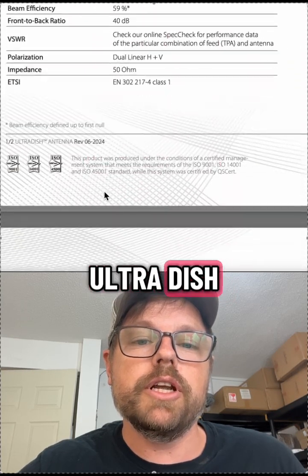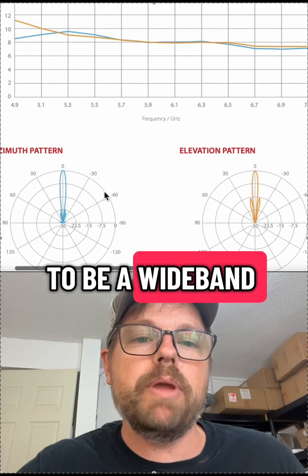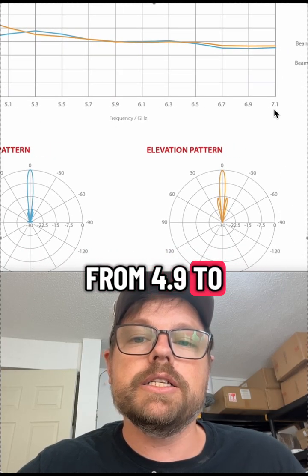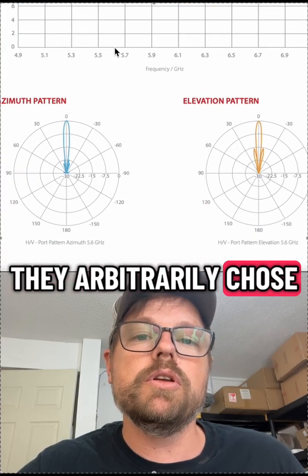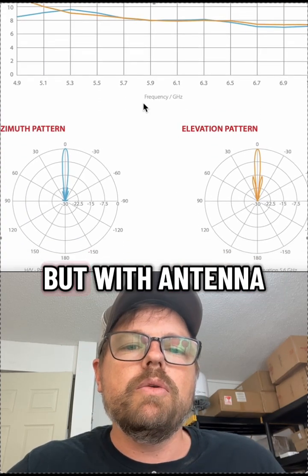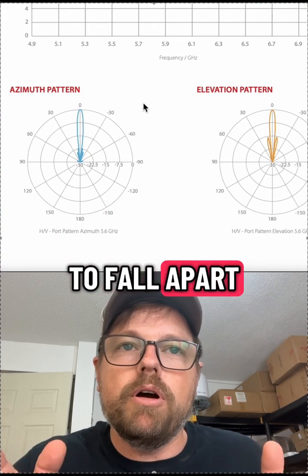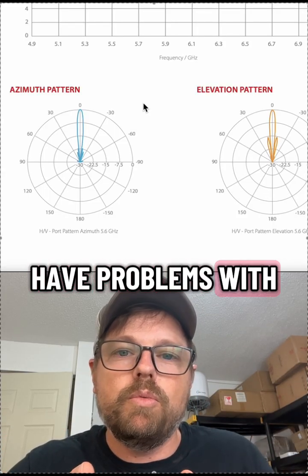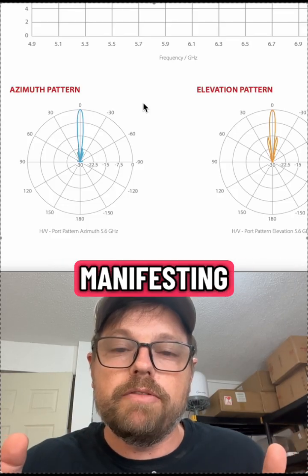This is the Ultra Dish. This is supposed to be a wideband antenna operating from 4.9 to 7.1. They arbitrarily chose 5.6 as the frequency point. But with antenna patterns, they're most likely to fall apart on the edges. That's where you're most likely to have problems with the radiation pattern, with side lobes manifesting.